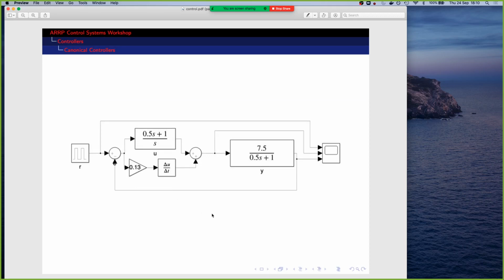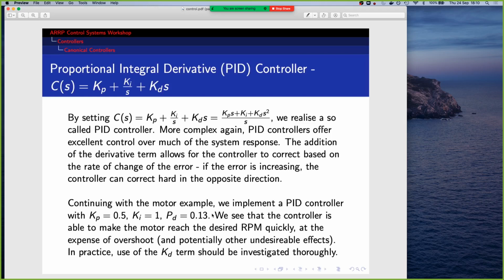What's the problem with transfer functions again? Is it something to do with causality? They are unstable and non-causal basically, or they're typically unstable. If you think about what happens at high frequencies with this one, it's sort of the easiest to see. High frequencies are for very large S. So if we let S tend to infinity, the numerator blows up, and our controller transfer function blows up as well.